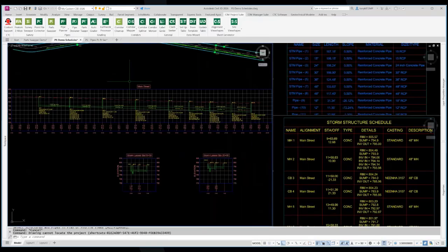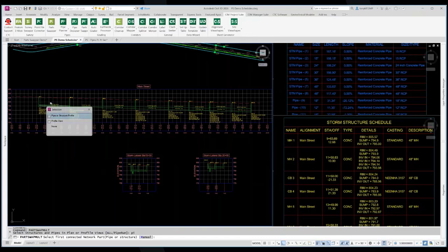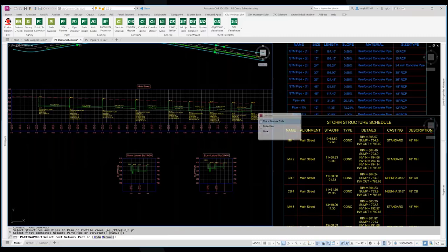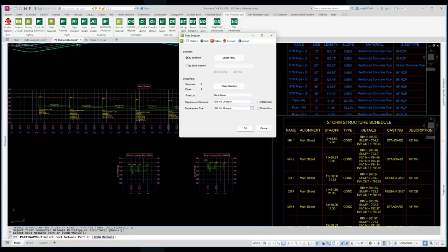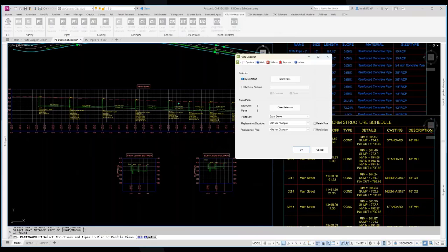Yeah, this is the one. Okay. Sorry about that. So if I come in here and I pick this and I say pipe run, I can do this manual by picking this one and then picking this one. And it selected this whole run right here, as you see. You can see they're included in these lateral runs right here.